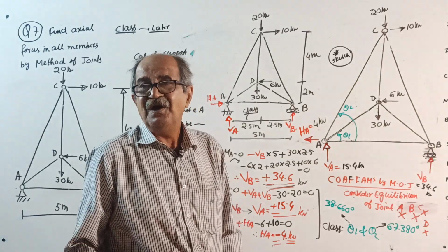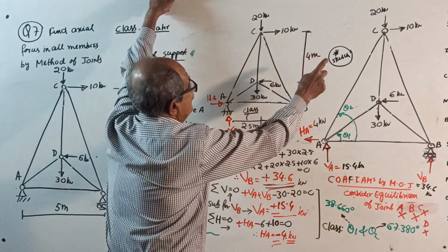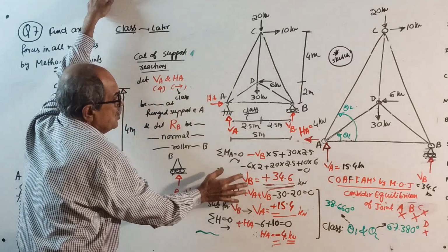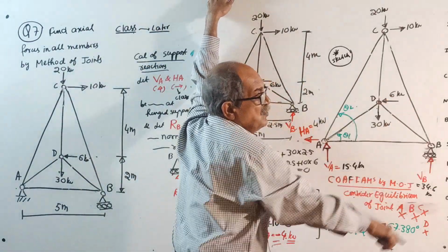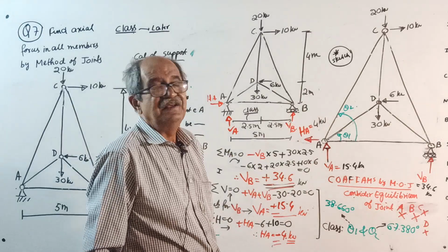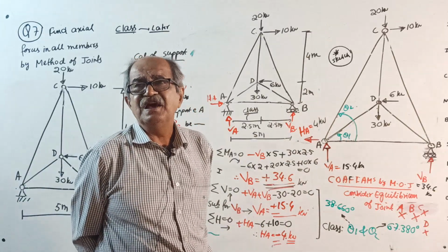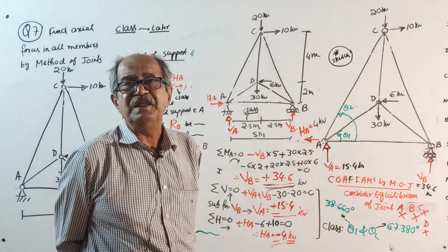See, I will tell you one thing. This question, problem here, support reactions, all sketch in one page. This all I want in one page because this is going to be cancelled. This pin-jointed frame is statically indeterminate internally to first degree.